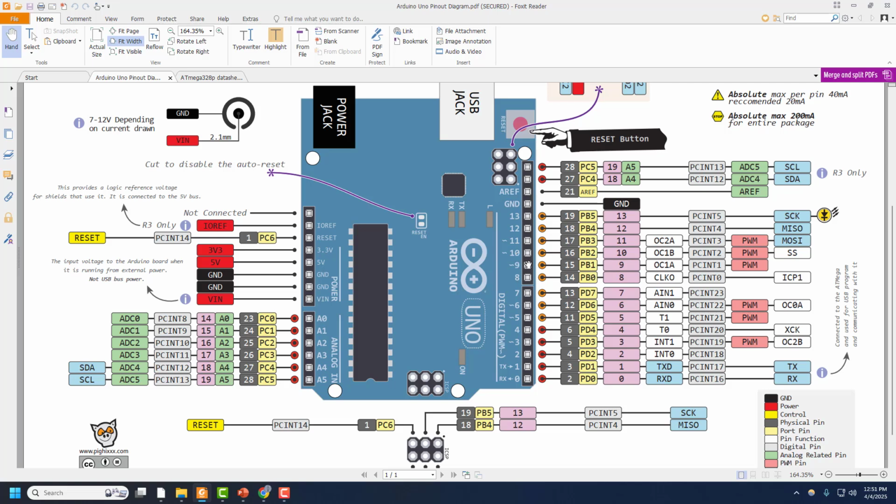If you understand that, then at least you know what's going on behind the scenes and why analogWrite doesn't work there anymore, whereas if you don't know anything about timers, that might just be a mystery. This can also become a problem, for example, when mixing third-party Arduino libraries or other Arduino functions that depend on timing, like the millis function, that might assume they have exclusive access to a timer.